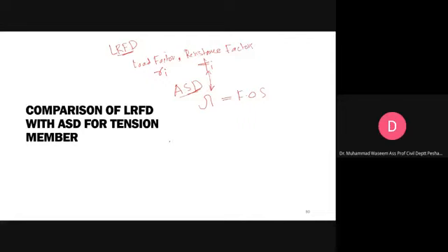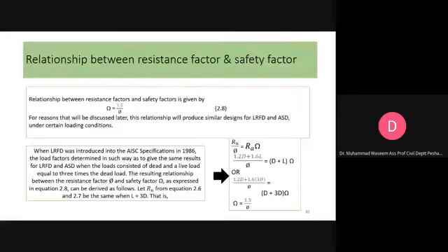So we will make a comparison between LRFD and ASD for a case of tension member. When we make this comparison, we come out with this relationship between the factor of safety from ASD and the resistance factor from LRFD.